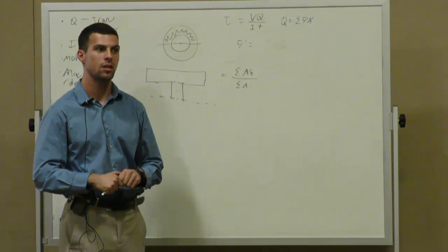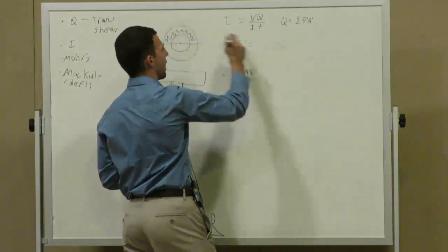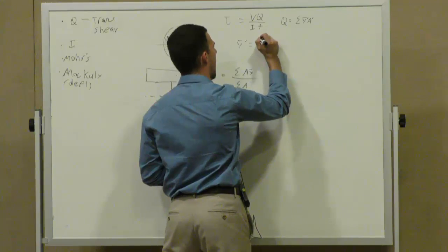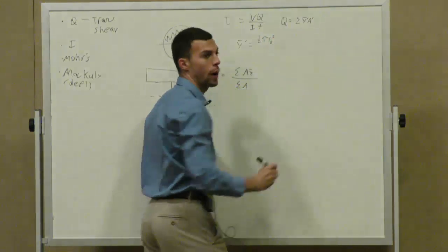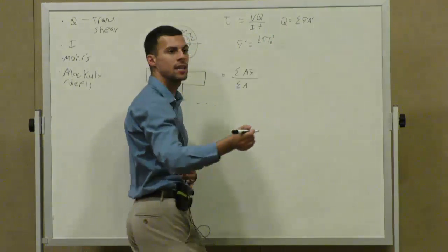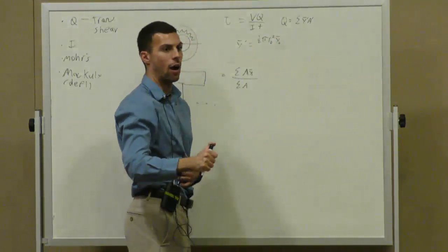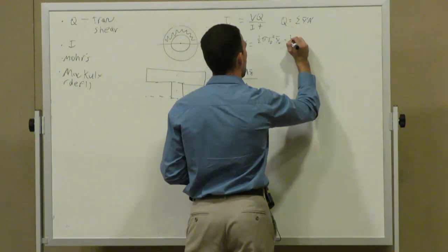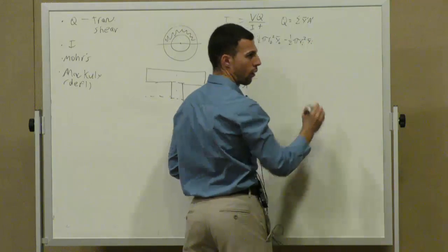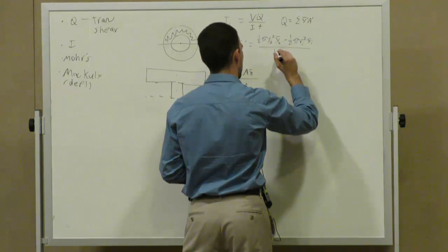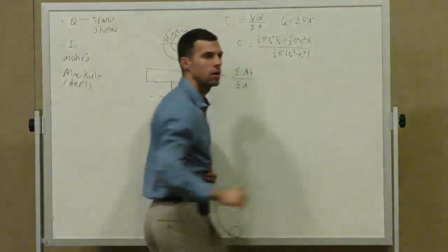Does that make sense? So in other words, for this guy, you'd have the outer ring. So you'd have area of a semicircle, which is 1/2 pi outer radius squared, times his centroid, his y bar for the outer, minus 1/2 pi r inner squared times y bar inner, over 1/2 pi times r outer squared minus r inner squared.